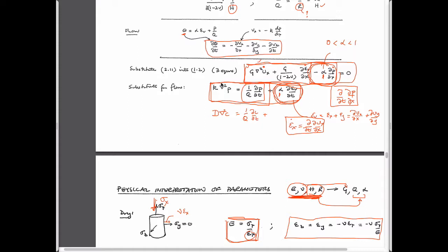But if you look at this expression here, this term here is saying something about the change in volume of this system as a function of changing the fluid pressure. And it only results from the change in fluid pressure. So you can think of this as really being something that acts on the compressibility of the fluid to be able to give a volume change in the system due to the fluid pressure change.